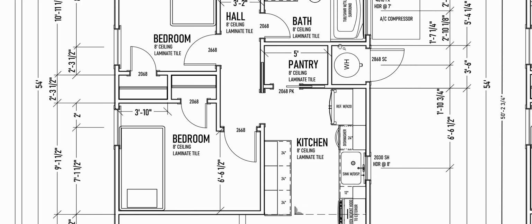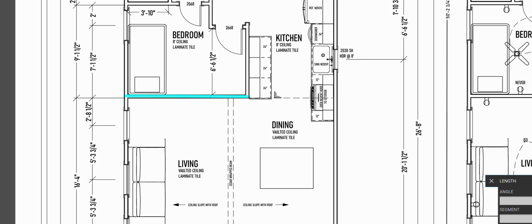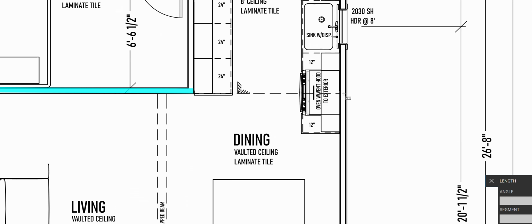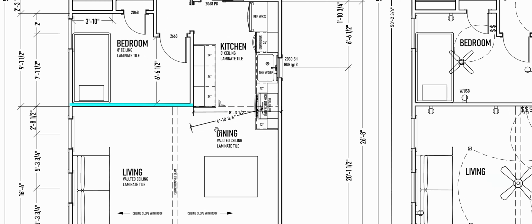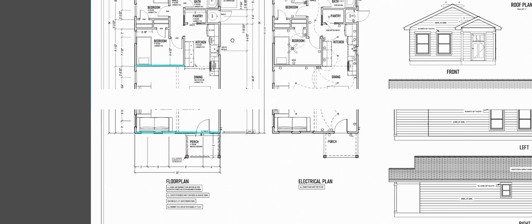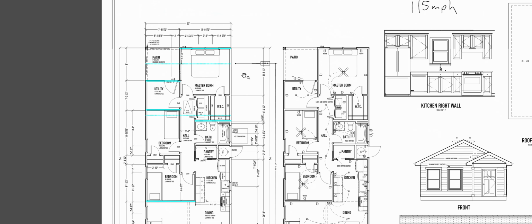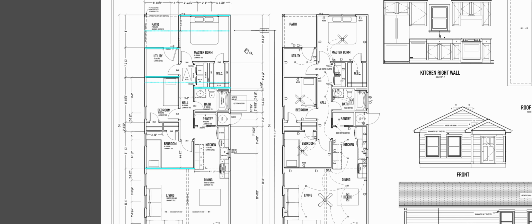Now, what I could do is technically I could have the braced wall line be this, if I could get something to start within 10 feet of my wall here. So what's my distance? I could claim this as long as I follow that rule. So here to here is 8 feet. Oh man, look at that. I like that. Okay, so I'm going to claim that wall. That's a little bit better. Okay, so I got 1, 2, 3, 4 brace wall lines to cover.